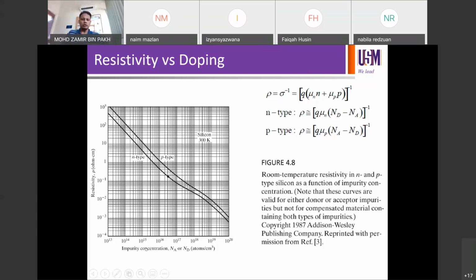So if I pick randomly, it means my doping concentration will vary from 1E15 to 1E16. So that means it's quite wide, it's quite broad in terms of the doping concentration. If my project works on the doping concentration, that means I might have some variation in the sample already before working on the device level. So you have to be careful then.